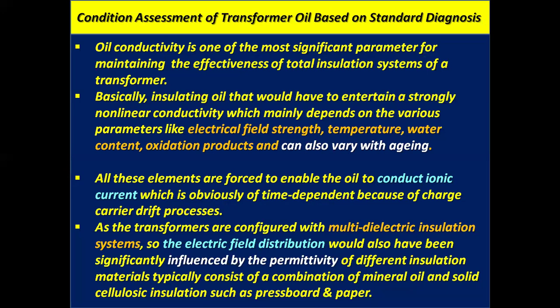Basically, insulating oil has a strongly nonlinear conductivity, which mainly depends on various parameters like electric field strength, temperature, water content or moisture content, oxidation products, and can also vary with aging.